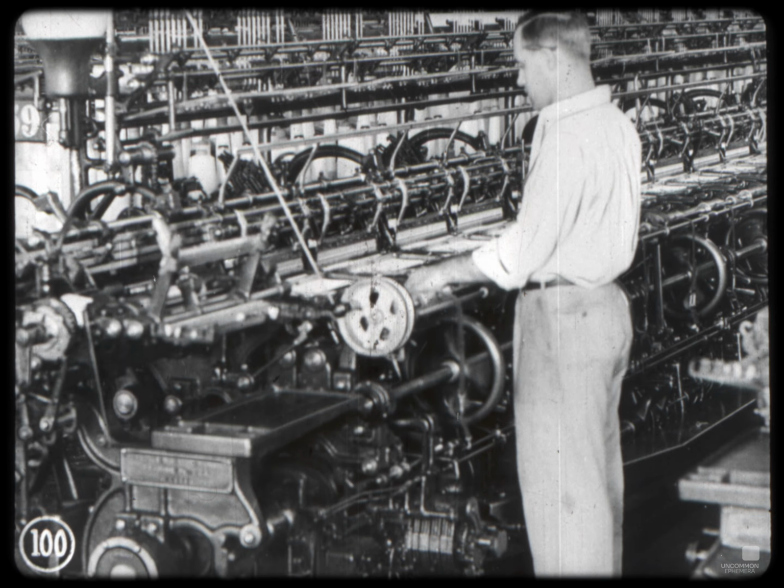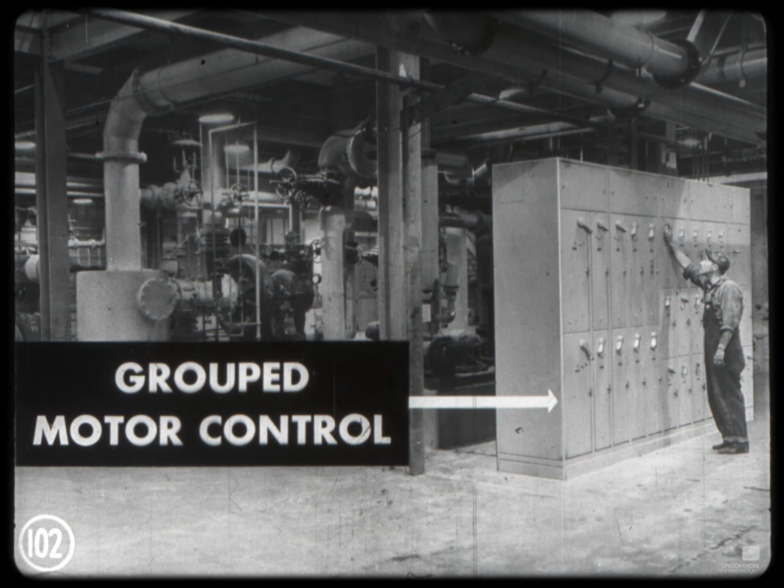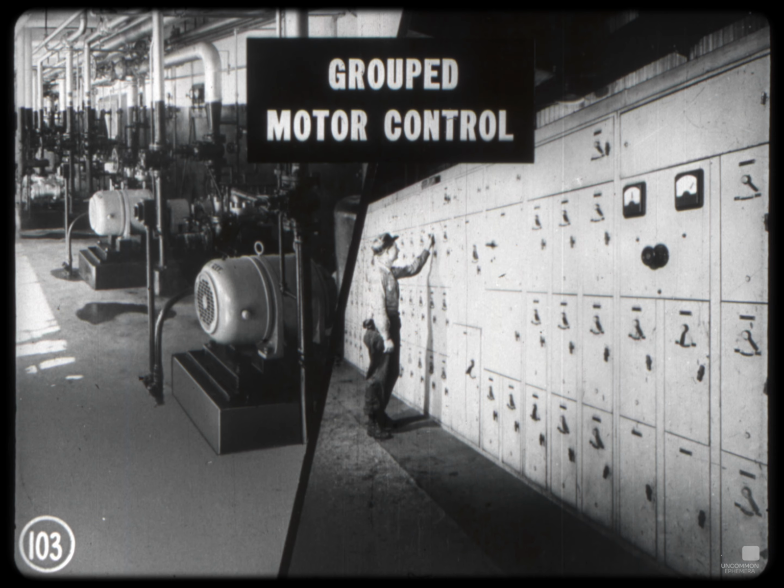If the application involves a group of motors, often it's more convenient and economical to put all control equipment for the motors in one grouped motor control location, such as in this sugar factory. This is often true in hazardous locations like refineries, too, where it may be more expensive to provide special control enclosures for each unit located near a motor. All control is located in a pressurized room or away from the danger area.